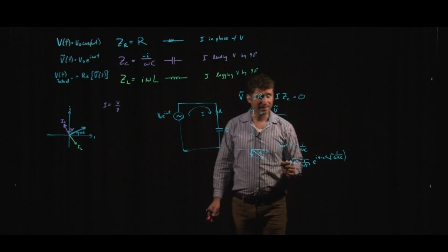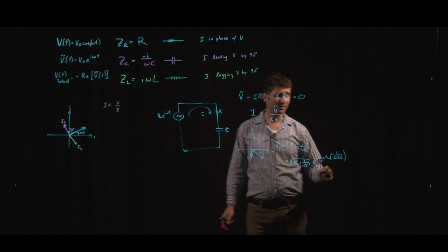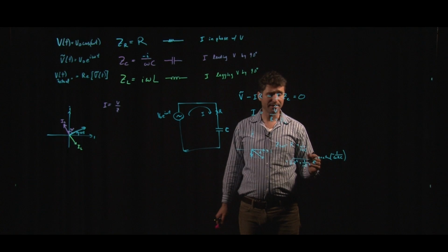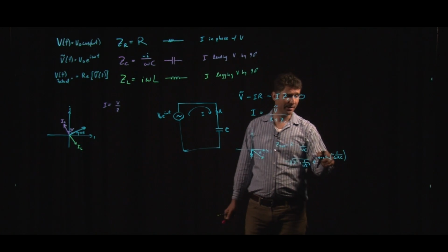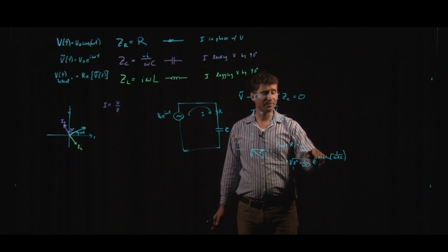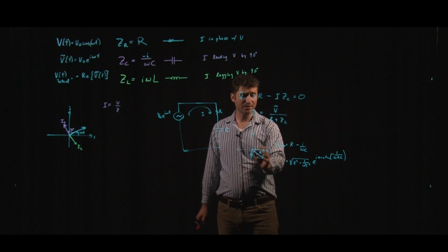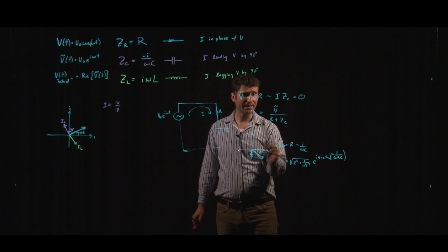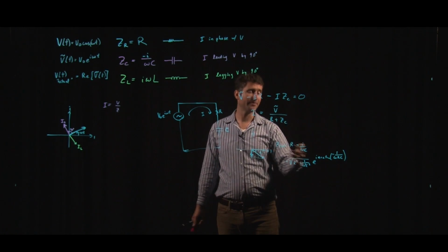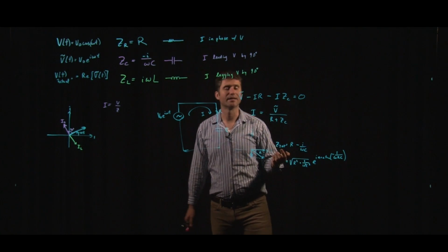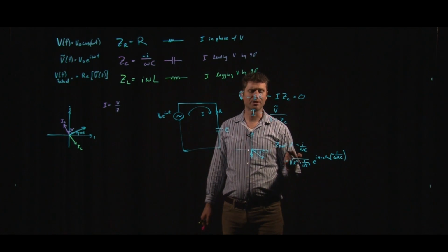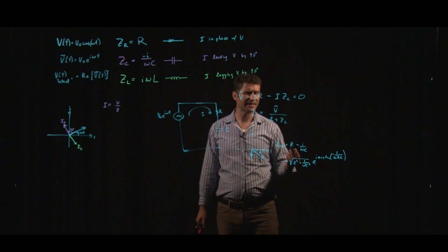So that's my phase. This is my complex phasor notation here, and one of the properties of arctan is that I can bring this minus sign out if you'd like. In any case, we can see visually that this angle should be negative, so that when we do 1 over that, we end up getting a positive angle, meaning we should get a phase lead.